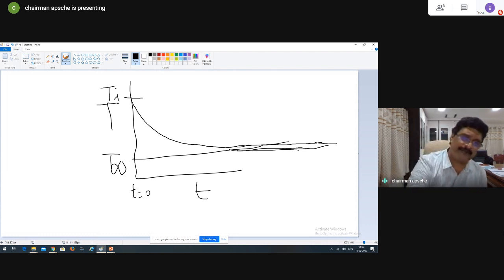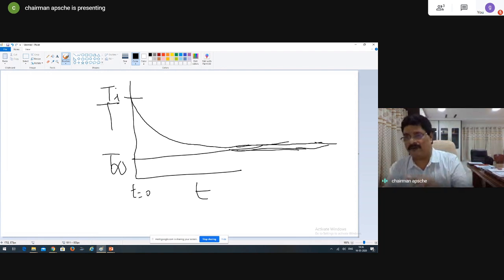But the majority of the temperature drop would have occurred in a limited time; thereafter, the fluid and the lumped body both take a long time for the temperatures to become equal. That's what exponential variation of temperature means. So at least you cannot wait an infinitely long time. That's what I said. My problem is I should be using a thermocouple to measure very dynamic situations.